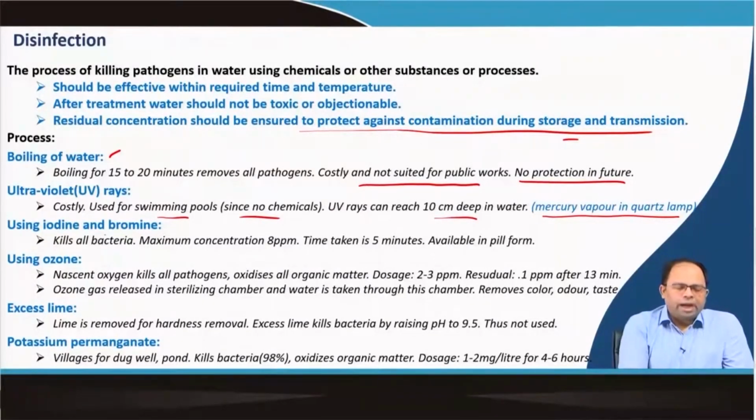We can also use iodine and bromine. This kills all the bacteria, and the maximum concentration that could be given is 8 ppm. Time taken is around 5 minutes, and it is also available in pill form.